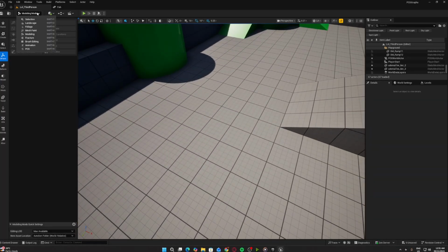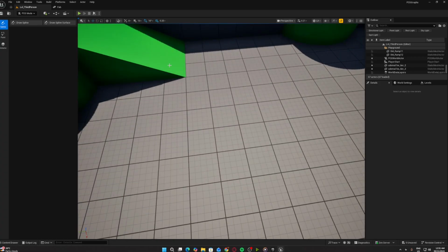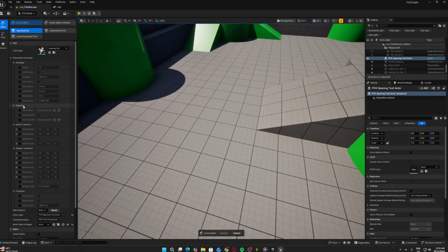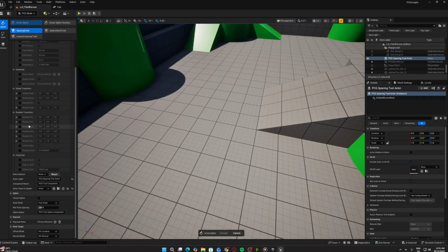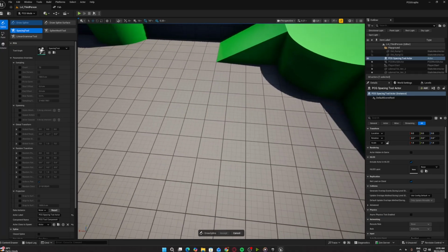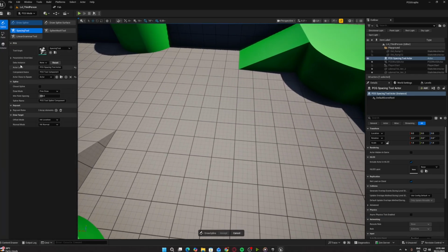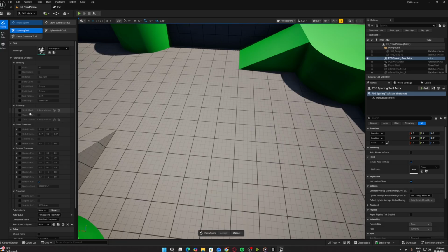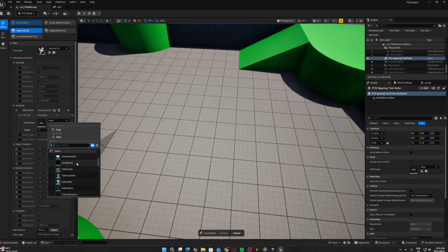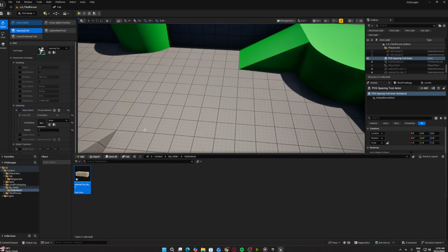What you're going to do is go back to PCG mode, in draw spline. Before we draw any spline, I would like for us to set up our static mesh. If you have your parameters open, in parameters override you can set your static mesh to the static mesh that you have created. For me, before I actually bring it in, I would like to rename this to sm_brick.